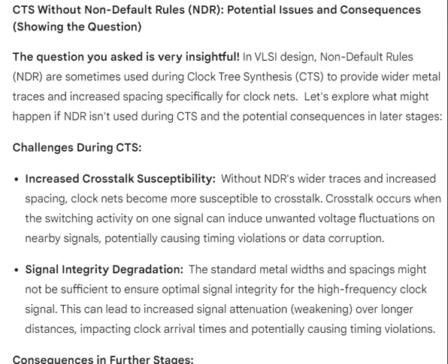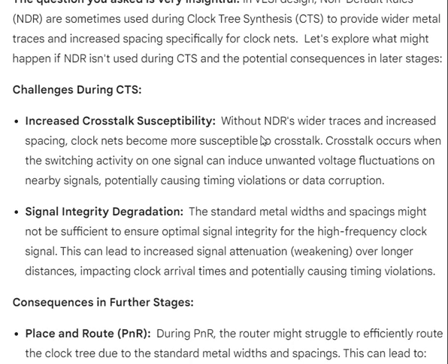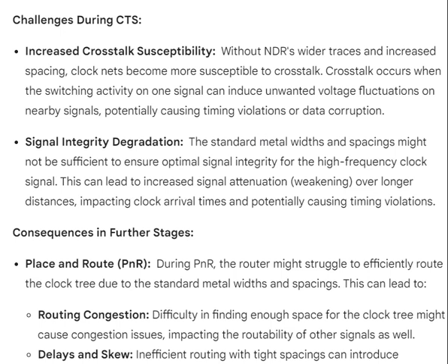CTS without non-default rules, NDR, potential issues and consequences. The question you asked is very insightful. In VLSI design, non-default rules, NDR, are sometimes used during clock tree synthesis, CTS, to provide wider metal traces and increased spacing specifically for clock nets. Let's explore what might happen if NDR isn't used during CTS and the potential consequences in later stages.